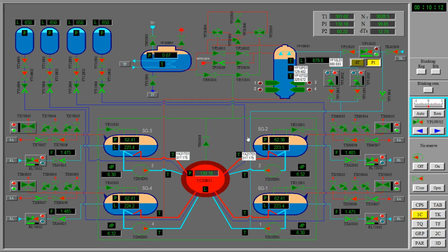And the pressure now is 130 in the reactor, 129 in the pressurizer. Why this differential? Because now water is flowing from the reactor to the pressurizer. And you may ask, why is it flowing? If it's water, it's incompressible. We don't have gas here. That's because of the elasticity of the structure, the pressure structure containing the water.